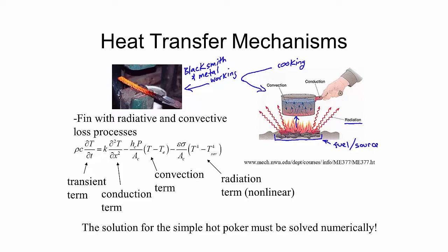radiation is primarily from the orange flames here. So these flames are shown as orange. What I talk about, for example, in a combustion class is that the orange glow of a flame is actually the soot particles within it. So there are solid carbon particles inside this flame.